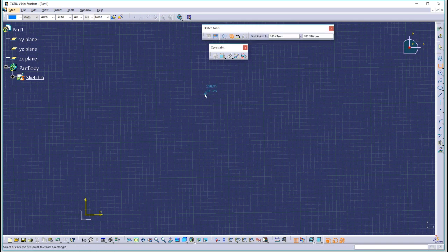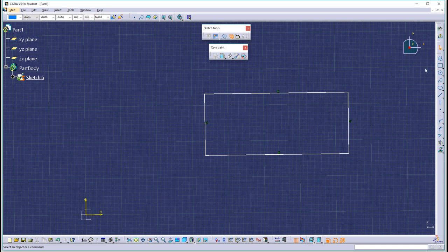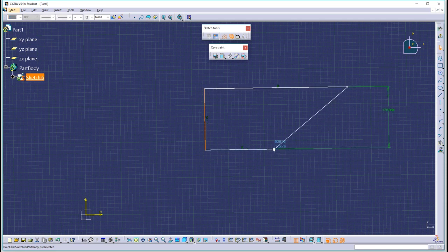Turn on geometric constraints. And now let's put an offset on. Select the constraint icon, and let's pick this line. Now by default it goes into length mode. But if you pick a second element, it gives the appropriate dimension. Now that is an offset, because if I delete this line, it's still there. It's still the offset between those two. Or Control Z to put the line back in. And even if I were to move this point here, this line could get longer, but that's still the offset.